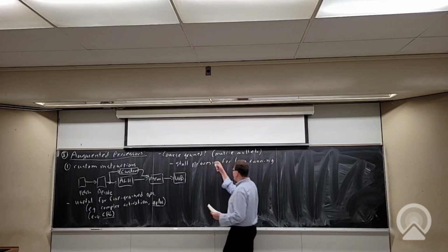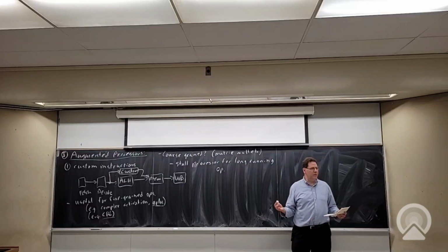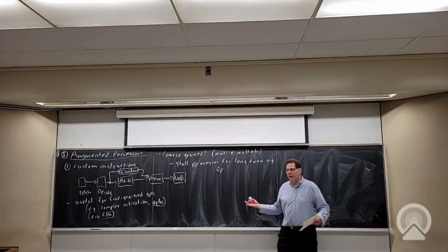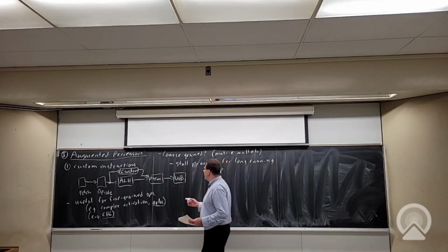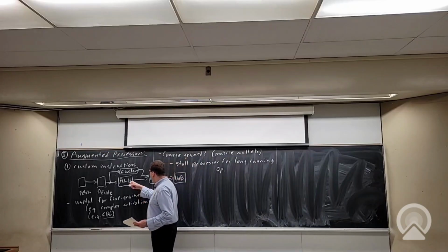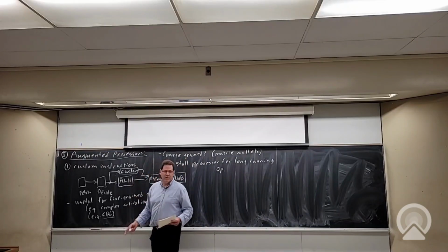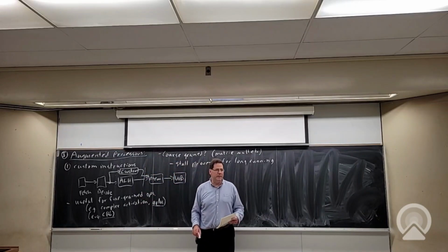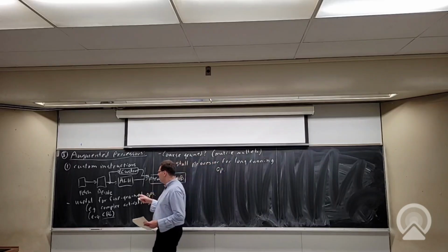Okay, so especially if this is a big matrix multiply, it's not going to execute in one cycle, right? Matrix multiply is an order n cubed operation for matrices that are n by n. So unless we do a really small matrix, this is going to run for quite a few cycles. While it's running, these are relatively simple processors, so we're going to stall, right? We're going to say, this thing's not done yet, still working, the processor will stall.